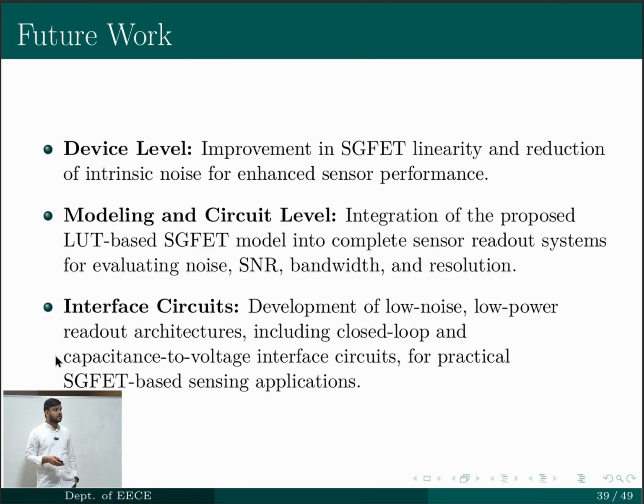At the circuit level, it can be incorporated in a sensor readout circuit, which can be used to calculate the signal-to-noise behavior, bandwidth and resolution. And as an interface circuit, it can also be used as a CV converter, meaning a capacitance-to-voltage interface circuit. These are the practical aspects of the device.